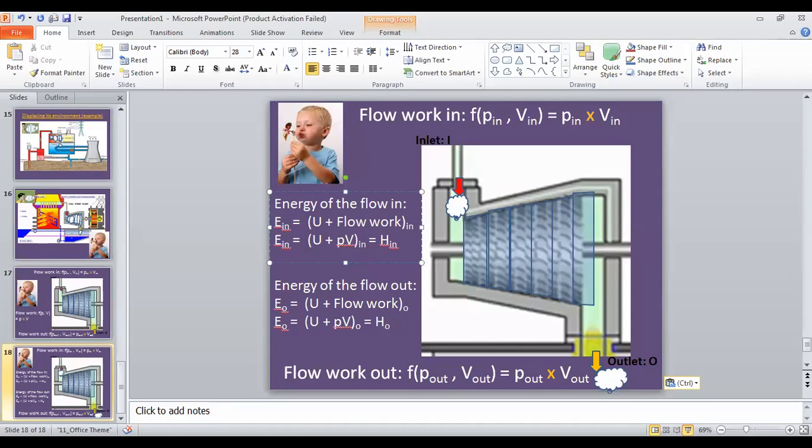So under high pressure, there is a potential for this flow movement because of the high boiler pressure, and also the lower condenser pressure. Condenser pressure is lower. They're both possible because of the turbine and the pump here. The pressure difference is maintained, and the boiler pressure is maintained because of the thermal energy delivered by the furnace here.